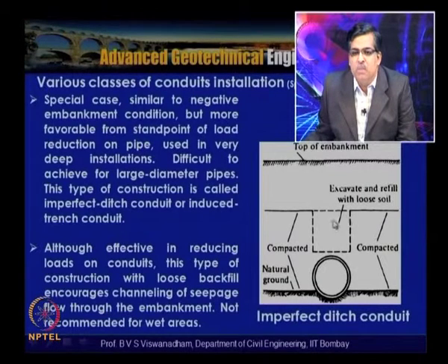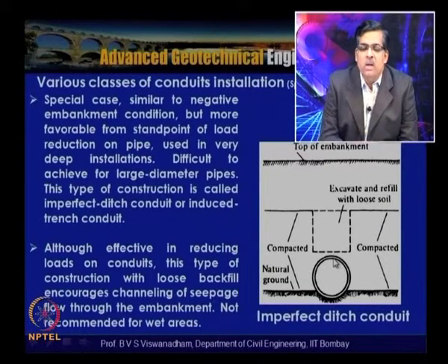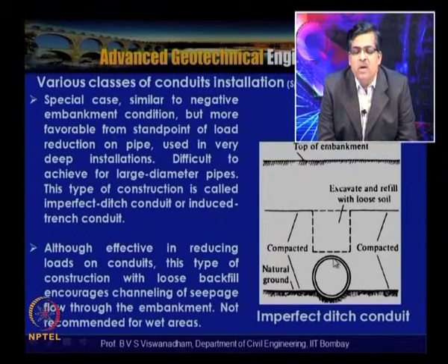So for example, this use of loose fill is effective in reducing the load on the conduit, but this type of construction with loose backfill encourages channeling of seepage flow through the embankment, hence it is not recommended for wet areas.